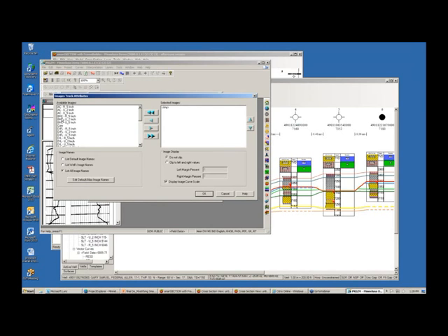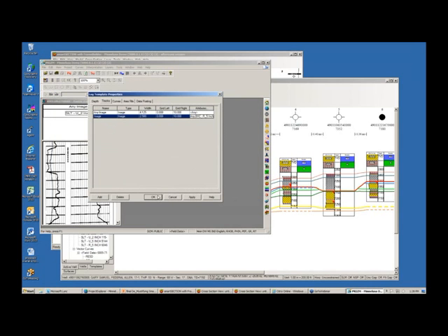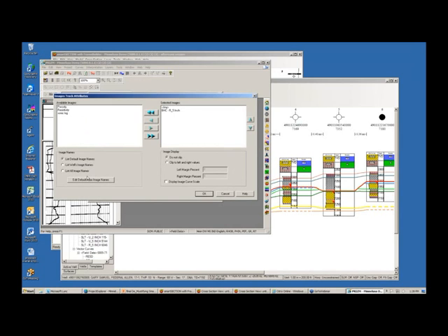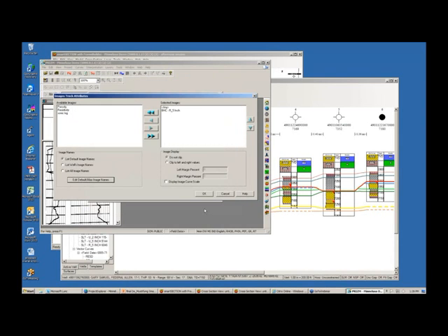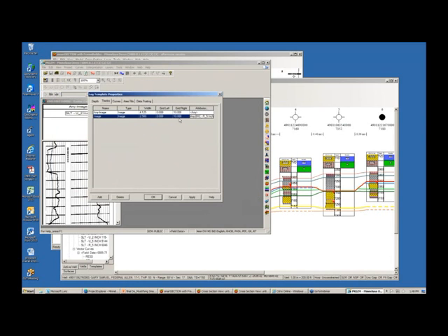And in addition, we now have the ability, in the lower left of this dialog right here, which was up for a moment, oh, sorry, go ahead, John. To alias your image names, which you couldn't do in Crosssection. So if you've got 400 raster image names, 30 of which are neutron density log types, you can alias them all to one default neutron density name. So you no longer have to build a raster template that has 25 or 30 potential log names in it. So I just wanted to make that comment.